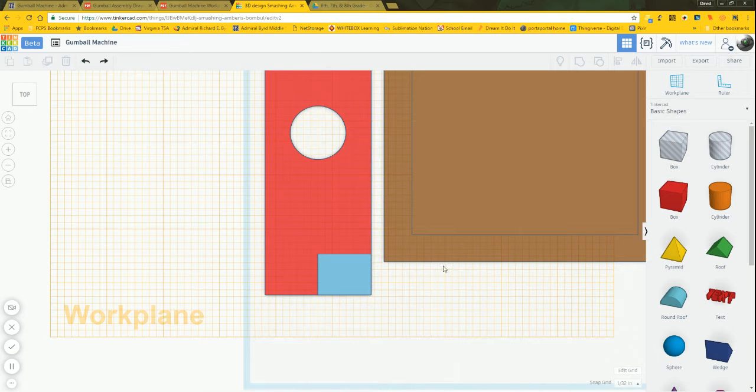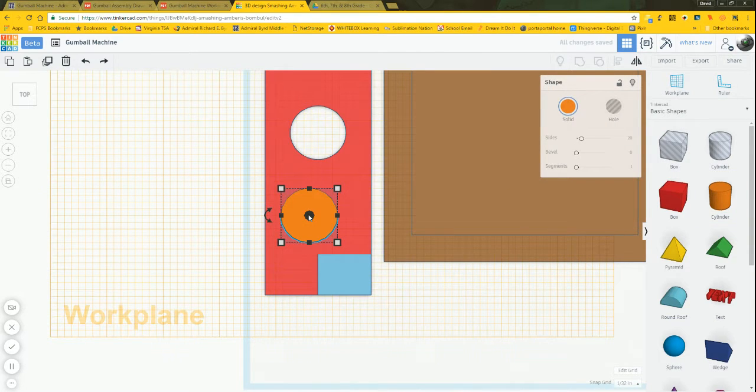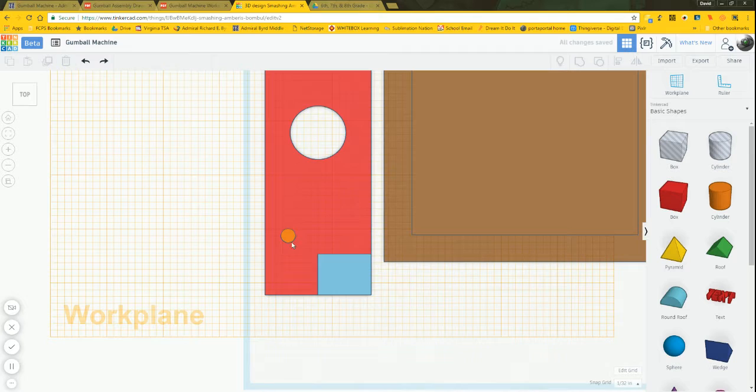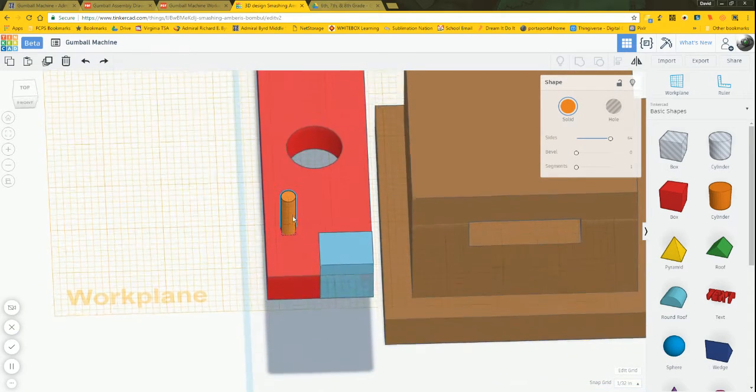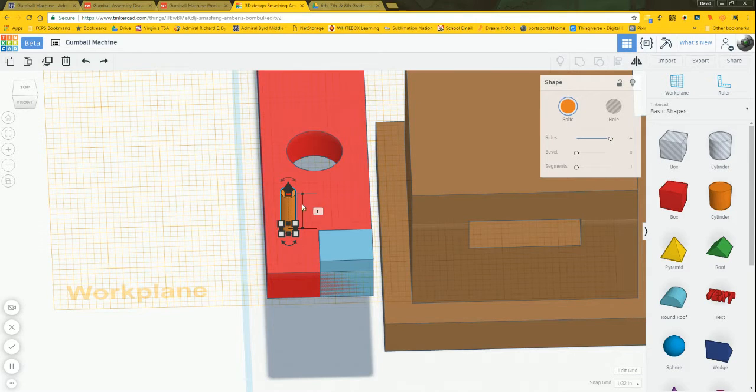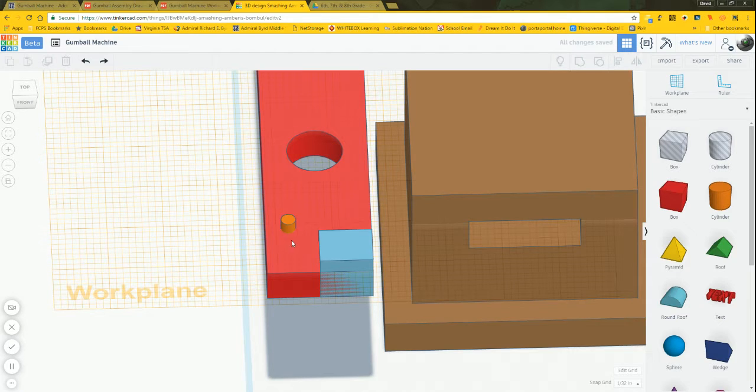So back to Tinkercad. Bring over a solid cylinder. Same thing with the sides again. You can drag it clear up so it looks more like a nice round cylinder. 1/4 of an inch, so 0.25. Wait till you get both in, 0.25, enter. There's my 1/4 of an inch cylinder. Default is an inch tall, don't want it. I need 1/4 of an inch again, so 0.25. Here we go. Kind of like before, I just have to set it so it's right on this corner, centered over that corner.